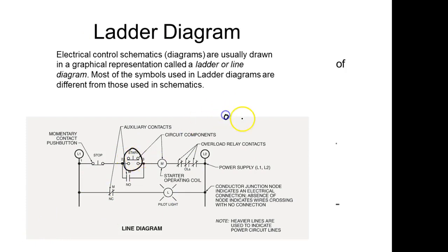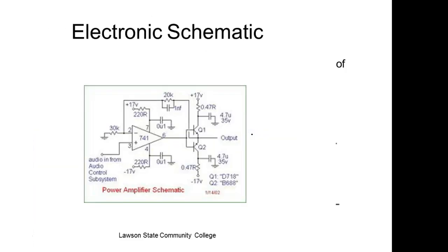A standard normally open push button would look like this. But they have that other setup here, which means I could use this as a normally closed, or I could use it as a normally open. Normally we don't use it for both. That makes sense? And we do have some of these push buttons over there on one of our push button panels.